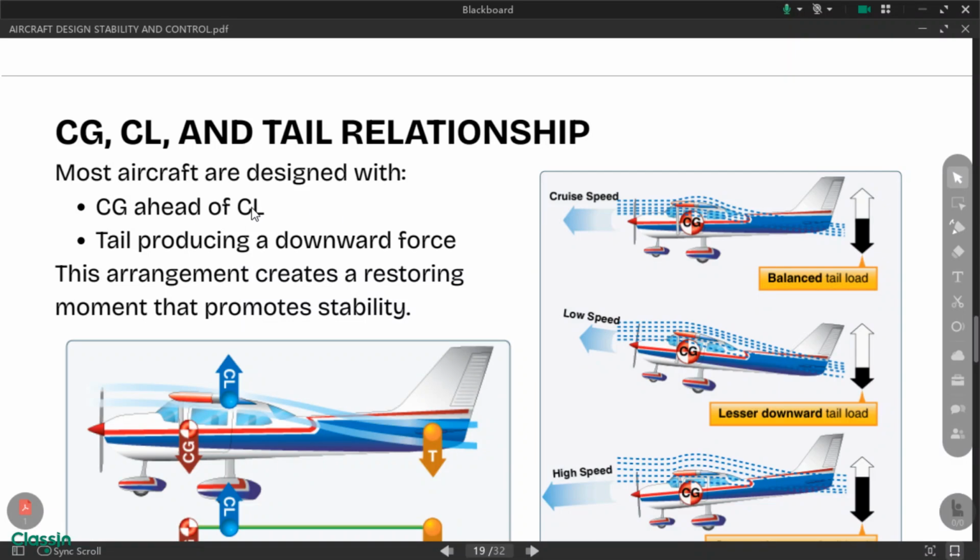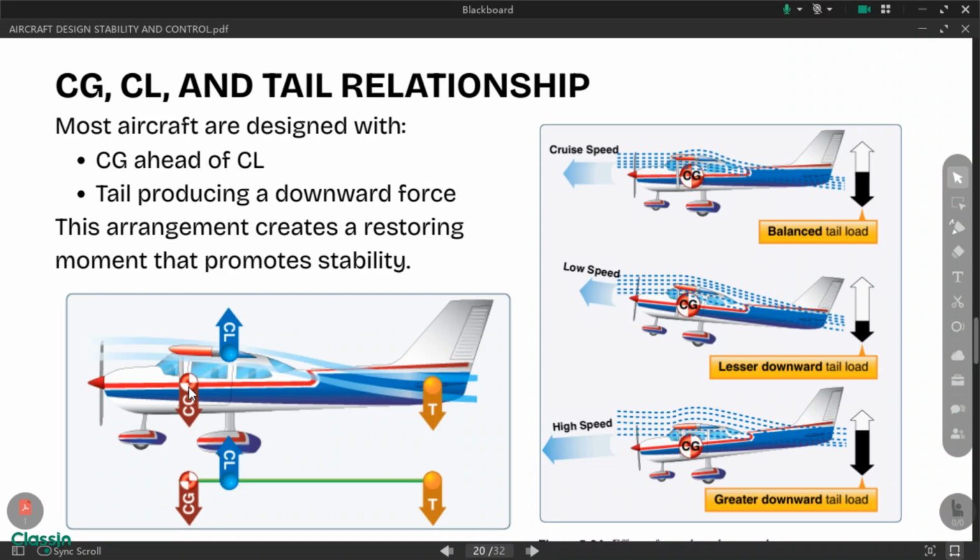So more concepts now for aircraft stability. For most conventional aircrafts natin, they are designed with yung center of gravity ahead ng center of lift. Okay? This arrangement, again, intentionally creates a nose-heavy aircraft. At first glance, it would seem na undesirable yun, kasi ba't nose down? Why would the designer intentionally create an aircraft that is nose-heavy?